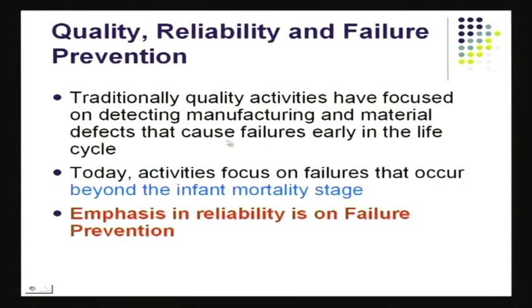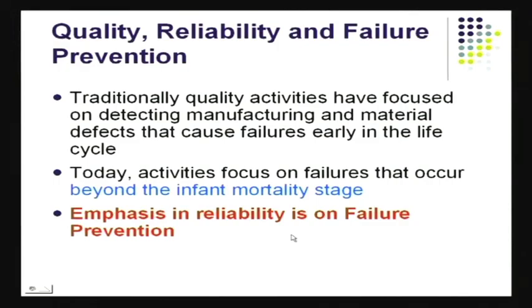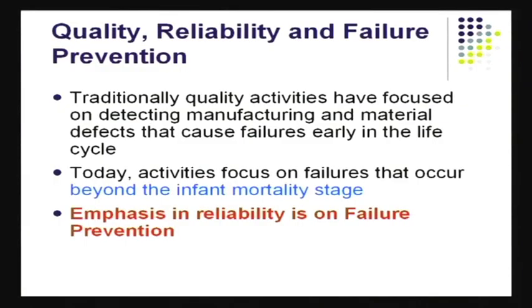The job of reliability engineering is to do whatever you can to try to reduce failures. This is the mission. And this is to be done beyond the infant mortality stage. We understand that infant mortality is because of manufacturing defects, as you are getting products straight off the line. Not many products will have these problems, perhaps just a few percent. But it's the period of use over which I've got to make sure that failures are few and next to zero if possible.